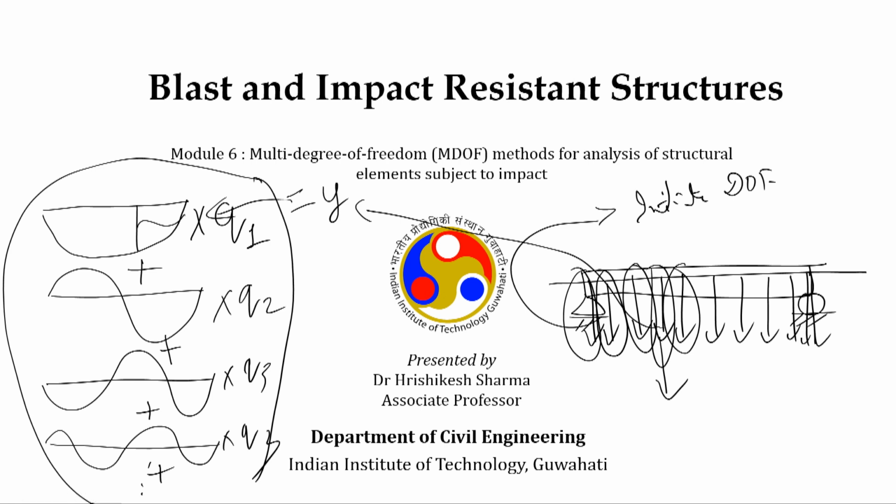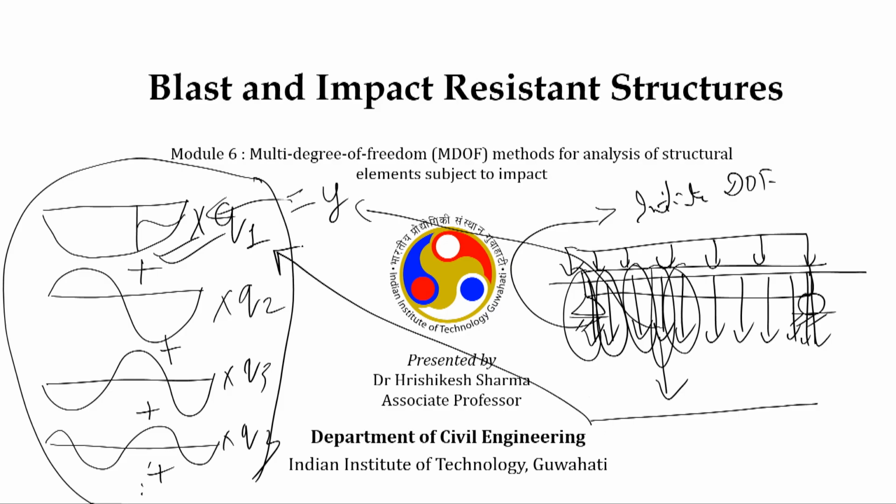When we started our analysis procedure, if we are interested in the maximum deflection, and if the applied load on this particular system is in this uniform shape, we argued that the first mode will contribute to a greater extent. Let us say this mode contributes 95 to 96%. Then we can analyze this system with 95 to 96% accuracy, but with much ease.